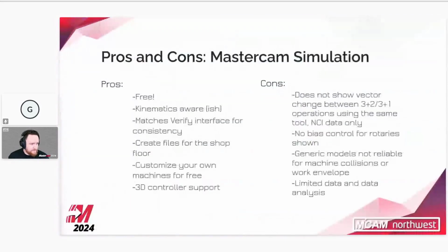All right. So the next thing to talk about would be the Mastercam simulation. So this is the free version of simulation that is built into Mastercam itself. The benefits of this is that it is somewhat kinematically aware. You can get the general idea of the kinematics in this. This also matches your Verify interface.